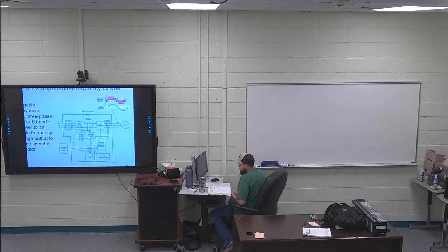I've got the heading of the second bullet point up in the top right of page 27 highlighted: constant torque loads, along with the second to last sentence in that bullet point. With these loads, the torque remains constant over the speed range, but horsepower increases as the speed increases. And then I also have the next bullet point, first sentence highlighted. Constant horsepower loads. With these loads, as the speed increases, the torque decreases, so that horsepower stays the same.